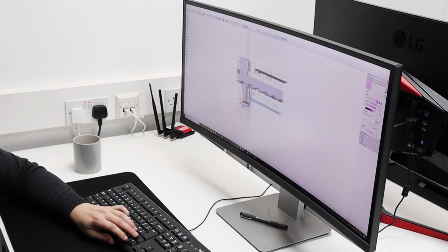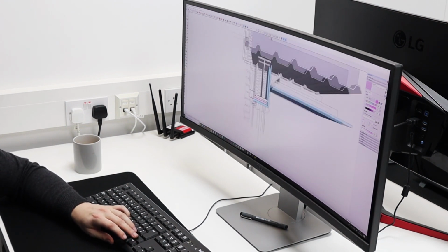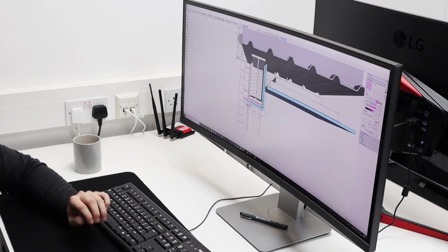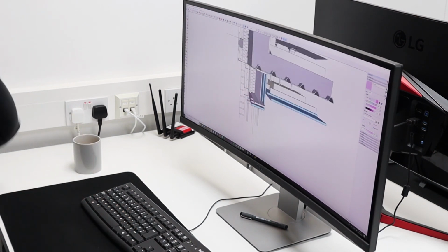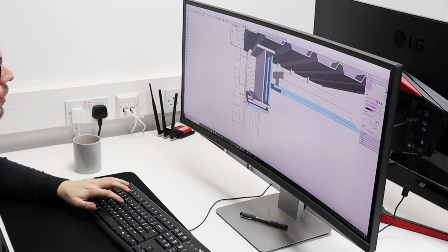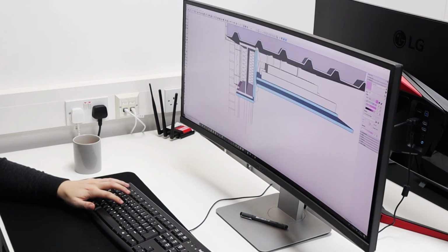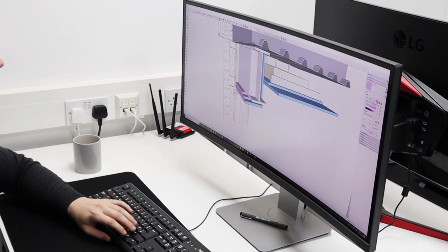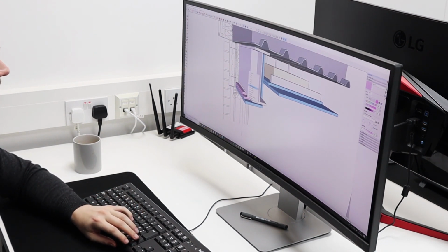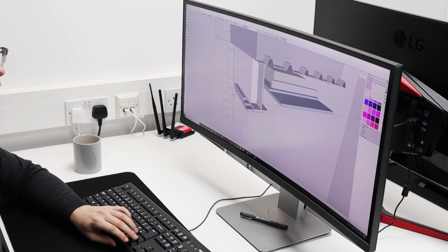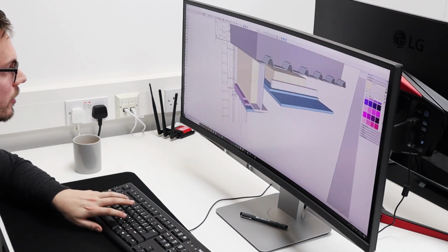And then we've got all this insulation up here, and that steel's forming a bit of a weak point. So what we always recommend is, that's what that insulation's representing there. We recommend that you completely pack the insulation again in a soft, malleable type insulation like a rock wool.